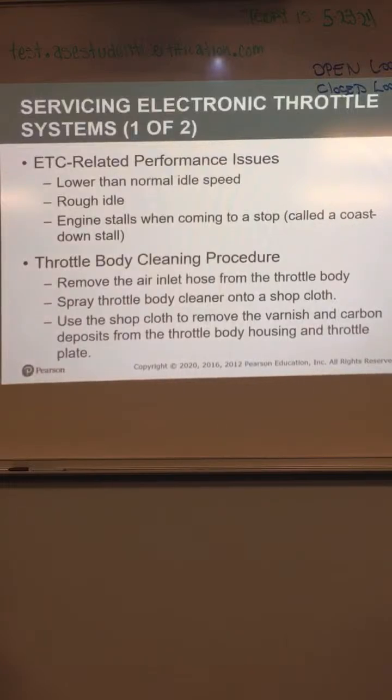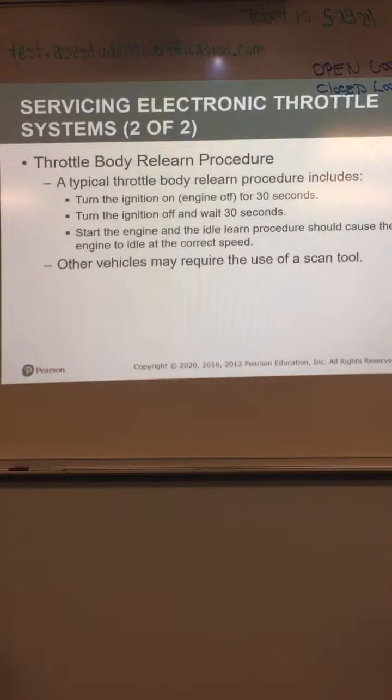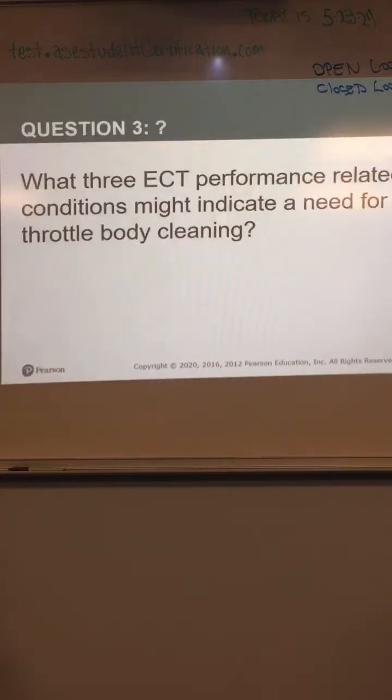Periodically, they will have to be cleaned to get the carbon buildup off. There's a throttle body air compensation percentage that it monitors. If the throttle body gets dirty, you will have to clean it periodically and reset the idle air compensation on it. The relearn procedure is pretty simple. The scan tool will tell you how to do that.